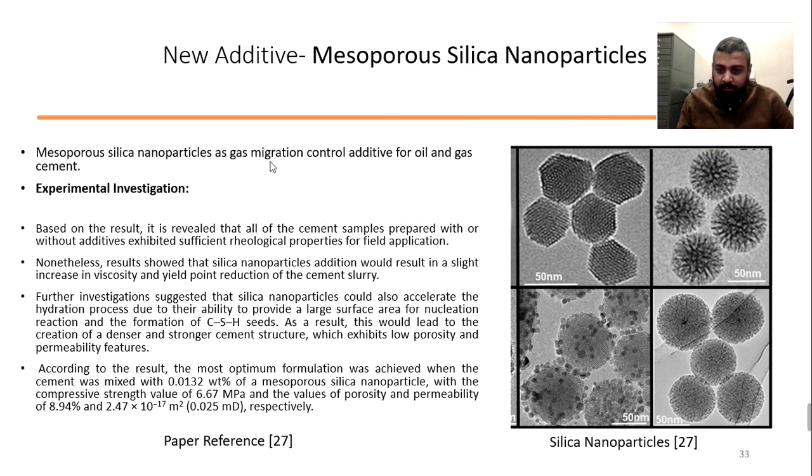This is quite effective for gas migration, because as you know, gas migration can happen through very tiny channels. So this one actually helps to control that gas migration very easily. Again, there is a paper reference, it's given in the end. You can download it from the lecture description. Okay, so in this case what they did, they created two samples, one with silica nanoparticles,